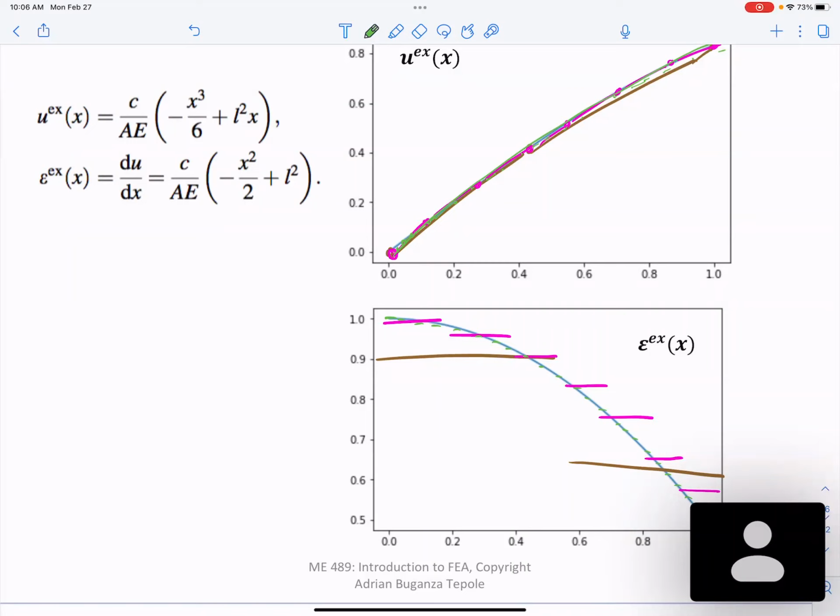So that's what you should try to do, especially if you don't have an exact solution. In lab 3, you had an exact solution for the stress concentration, so you could refine your mesh until you got a stress concentration similar to the analytical one. For cases where you don't have an exact solution, you should still refine your mesh, pick your location of interest where you have a larger variation of stress or where you expect the thing to fail, and just monitor the stress at that location.